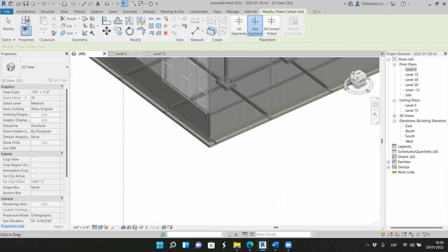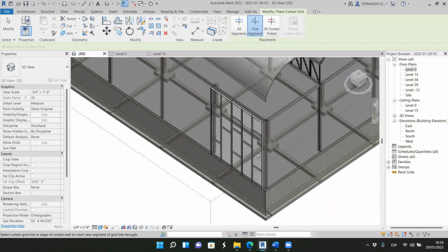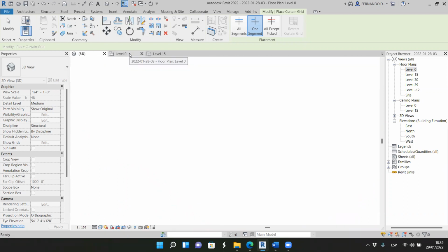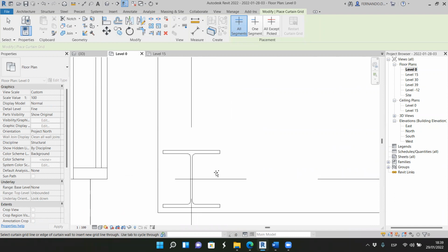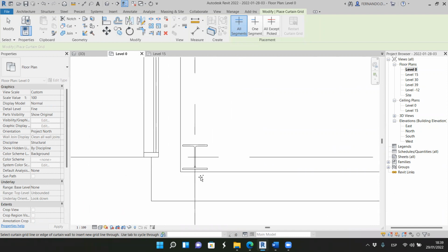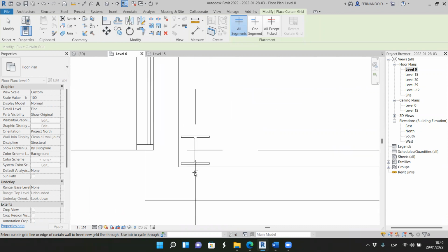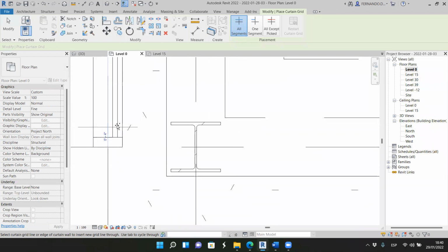So with this, there's a curtain wall here. Why did I do that? You see that I have not placed the curtain wall just here in this grid line. Why? Especially in these steel structures, we have to prevent the thermal breaches. Okay, so here the thermal insulation of a curtain wall is the glass itself.